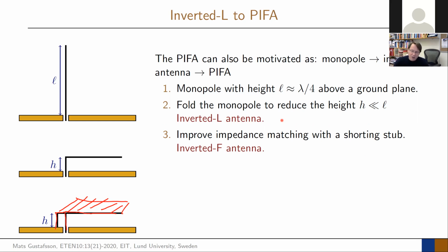It's probably easier for us to understand the function when we come from the patch antenna and the cavity model. The name comes more naturally when we think about this monopole, L to F, okay, planar wide, and that's the PIFA antenna. And when we do that, we can also see that, of course, I don't have to short circuit everything here and feed it everywhere. I can just pick some points, and I can start playing with the geometries.